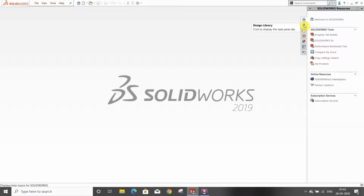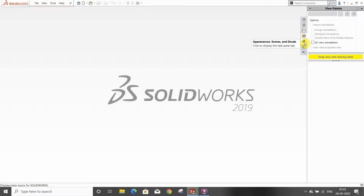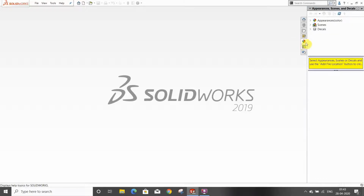Then this is the main, important thing, which is SolidWorks toolbox. From here you can access the design library, toolbox, 3D content center, and SolidWorks content center. Then there is the file explorer. From here you can access different files you have created. Then the palette viewer, it is used in the drawing when you want to drag and drop any view of your product into the drawing.